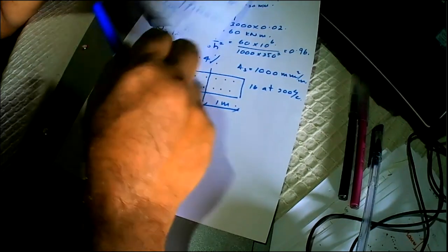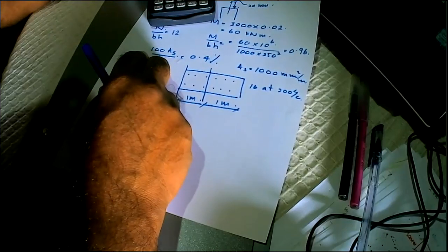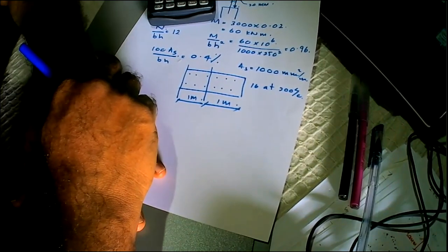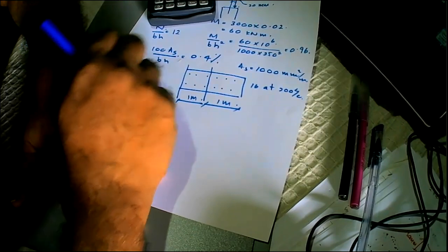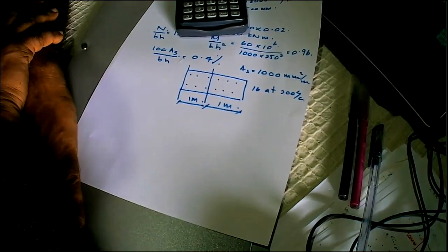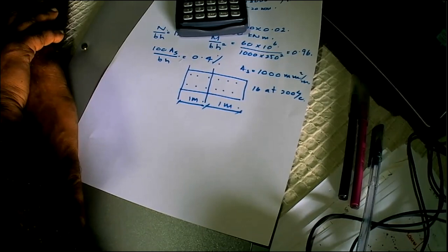So if tension occurs on that one side, what do we have to do? Yeah, if tension occurs, that means the wall will be cracked. Is that right? If tension occurs, we'll have a problem, because if tension occurs in the wall, that tension will be transferred onto the foundation. And generally the piles are designed to carry axial load, vertical load, or the compressive load. Is that right? But if tension can occur under the shear wall, then it's not a very healthy situation.